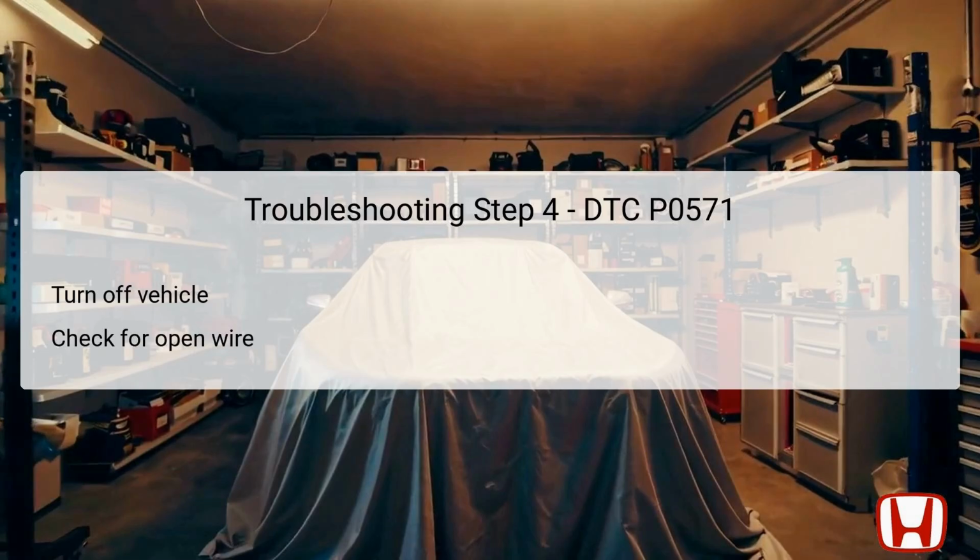In this fourth step, the vehicle must be turned to the off mode to conduct an open wire check on the stop SW line. The technician will use the Honda Diagnostic System, HDS, to jump the SCS line, allowing the diagnosis to proceed without faulty signals interfering. Disconnecting the PCM connector A50P is crucial before proceeding to check whether there is voltage at designated test points when pressing the brake pedal.